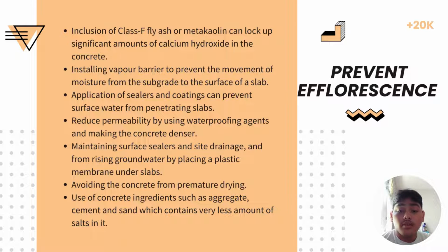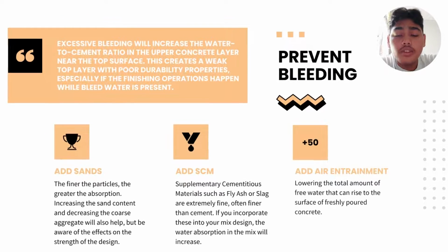Salt is a mild acid and lowers the pH in the concrete. The acidic reaction attacks the concrete paste and aggregate, weakening the structure and strength of the concrete. It also increases the pore size, allowing additional water and chemicals into the concrete, which can exacerbate freeze-thaw cycle damage. Last but not least,